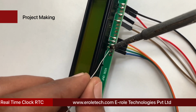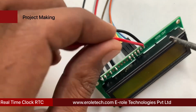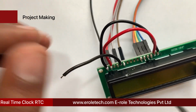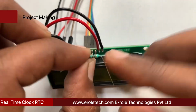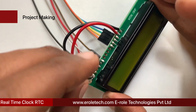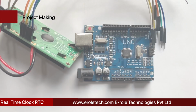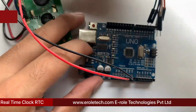Now connect hole number 16 with hole number 1 using a black wire, and hole number 15 with hole number 2 of LCD display using a red wire. Now connect hole number 5 with hole number 1 of LCD display using a black wire. Now connect hole number 3 with hole number 1 of LCD display through a 1 kilo ohm resistor. Connect the red wire with 5 volt pin and black wire with the ground pin.